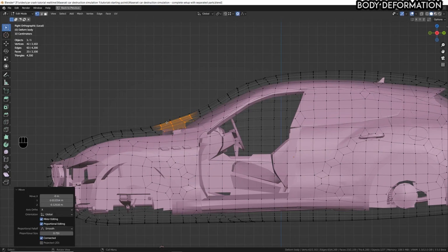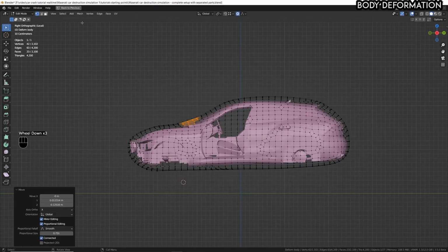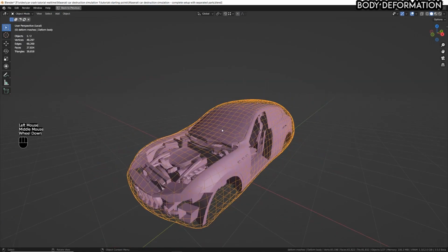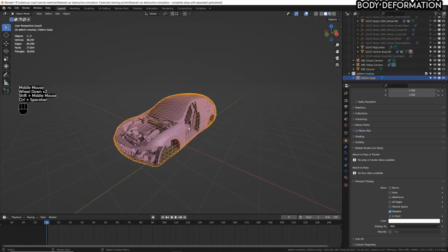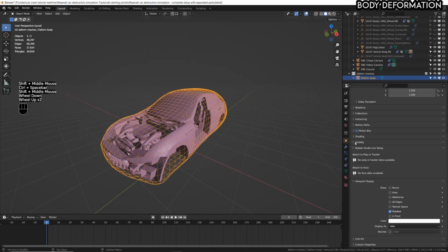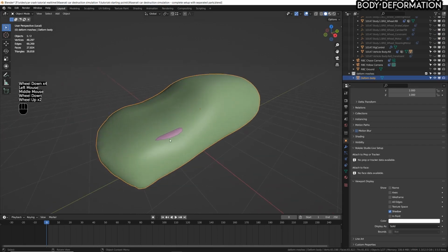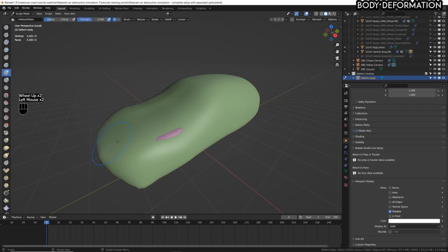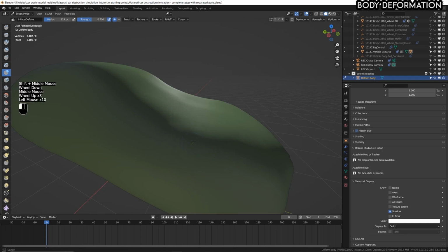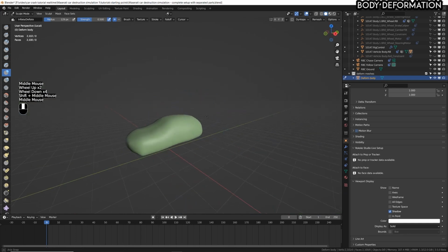Yeah, this is gonna be fine. And by consequence, I think we are gonna have to, let's go out from edit mode. We're gonna have to adjust a little bit more in sculpt mode. So let's check that there are no parts left outside again. So object viewport display as solid. And yeah, there is some little adjustment to do here. So sculpt mode, inflate tool, and just a little bit here, a little bit here, and this should be enough. All right, and we can finally proceed.